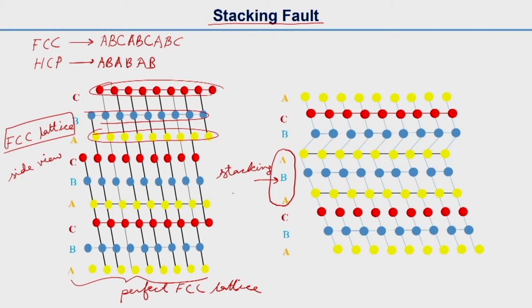In summary, a stacking fault is a fault in the stacking sequence of a crystalline material. You can check these basics in a materials science textbook. The stacking fault has a stacking fault energy, which I will write as E. All crystal defects, not only stacking faults but dislocations, grain boundaries and twin boundaries, have energy associated with them. A perfect crystal is at the minimum energy level, but these defects increase the energy.